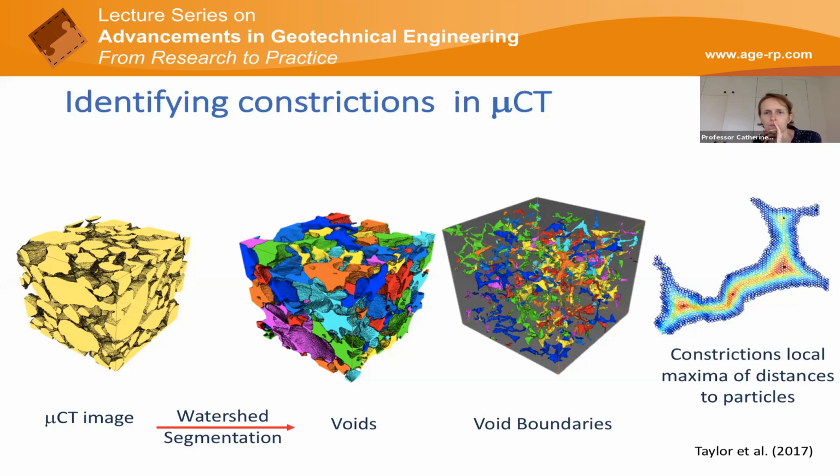Okay, this one comes from William from Valley, and he asked that if the infiltration of water into the soil particle, isn't it a mechanism for scour? The scour would be a surface erosion. So that would have a slightly different mechanism because the flowing water picks up the particles from the surface. And I don't quite understand the question about the water getting into the particles, but we are dealing with relatively low pressures here, so we're not at a sufficient pressure that we would break the particles.